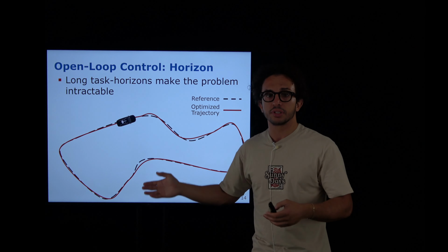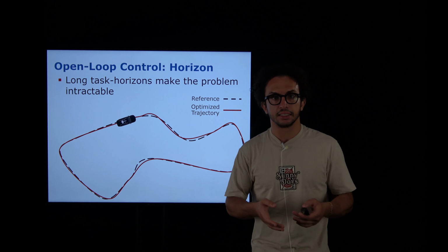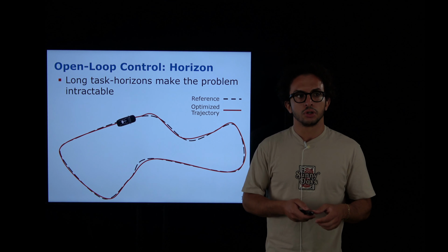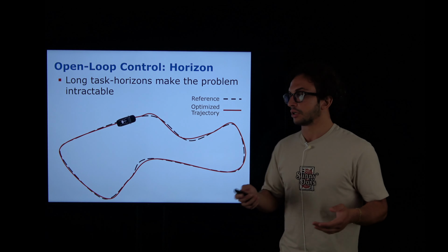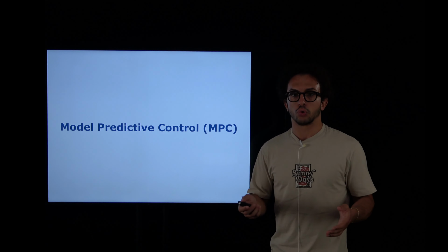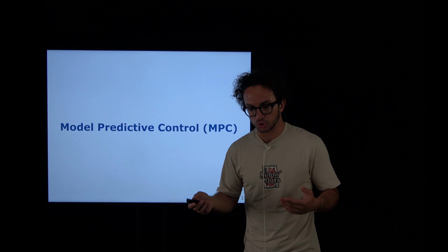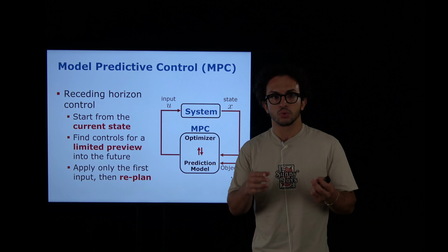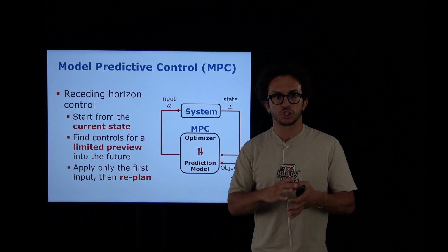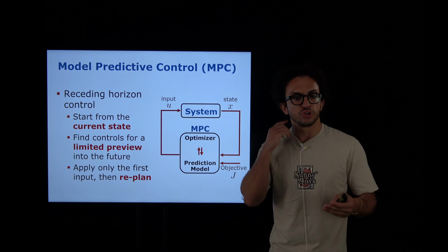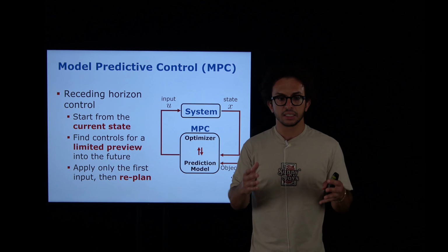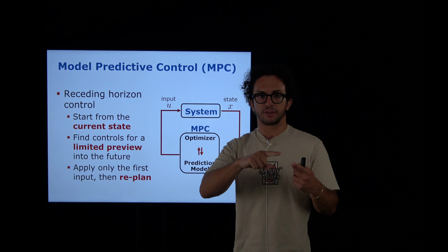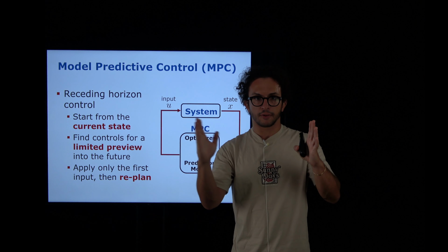You could still set up the optimization problem and solve it with CasADi, but then the solution you get is not aligned with your expectation. So we have to modify something. And here we have model predictive control. This is basically where model predictive control comes into play. Why? Mainly because it has one crucial concept, which is called receding horizon. This receding horizon basically tells you, I'm not looking at the whole trajectory and trying to optimize everything. I'm looking at a chunk of the trajectory.